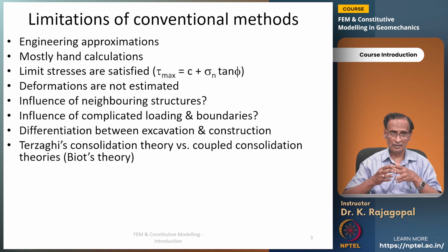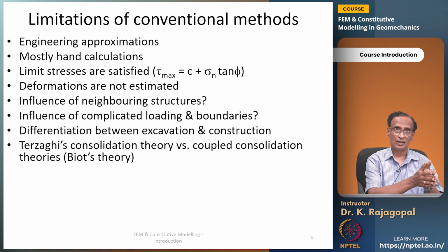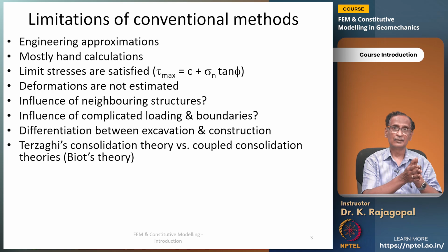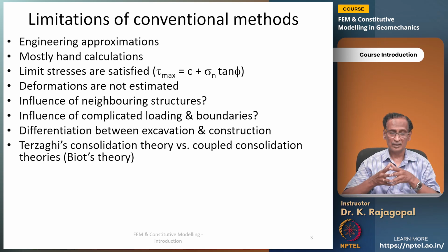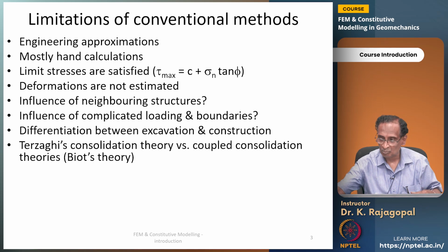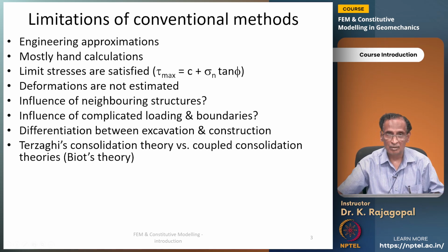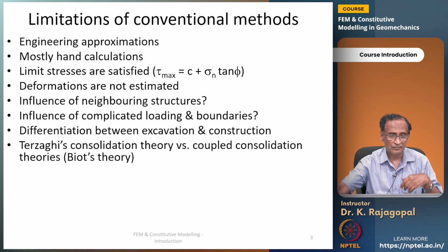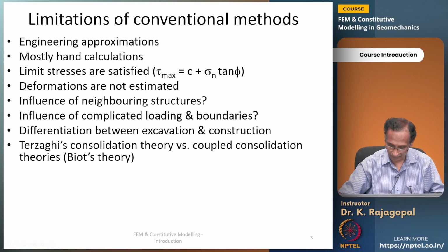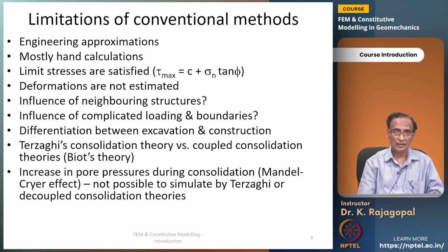And Terzaghi's theory, we call it a decoupled theory, wherein we predict the pore pressures separately, and then we estimate the degree of consolidation, and then we estimate the settlement at different times based on the degree of consolidation. Later we have more rigorous coupled consolidation theories, for example by Biot, and